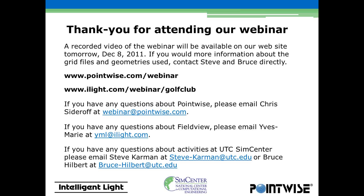Okay, thanks, Bruce. Here's another good one for Steve and Bruce. This is just a follow-on to Jason Mateer's original question. I assume when you calculate drag, you integrate pressures and viscous forces over the golf club head. Does resolving the vortices downstream have a measurable impact on this integrated drag? I can see maybe on a ship it would have an impact because of the length of the ship and the interaction, but for the golf club head?